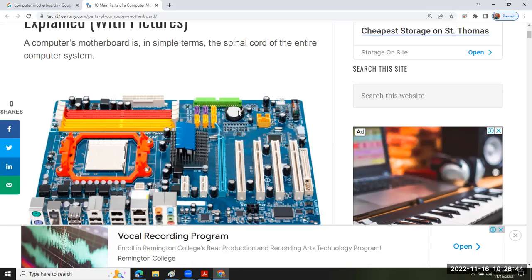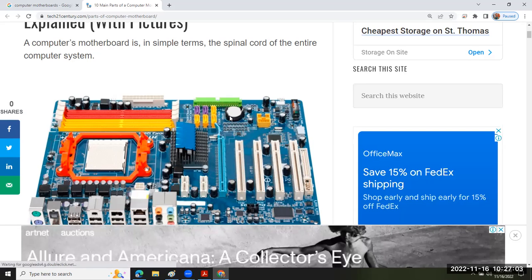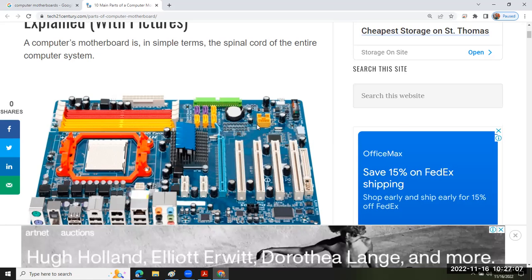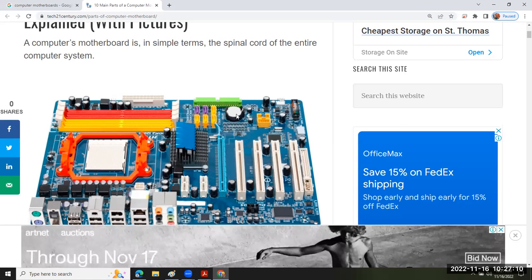Basically, your motherboards all have a battery that helps it retain the date and time. It's so that you can retain the settings of the BIOS. If this battery goes bad, the BIOS settings revert to default settings, and every time you power it on, you'll notice that it's some obscure date like 2010 or 2020, depending on how old.